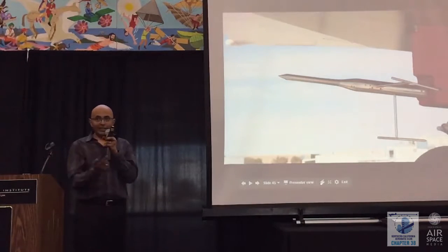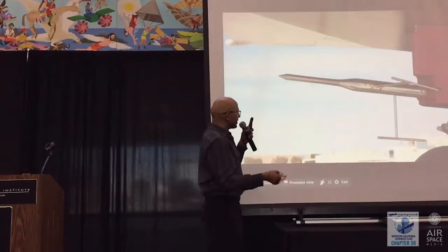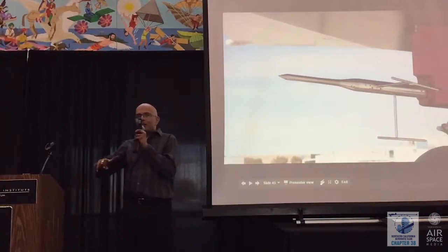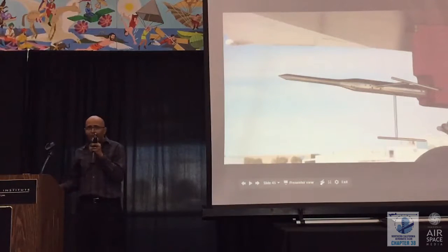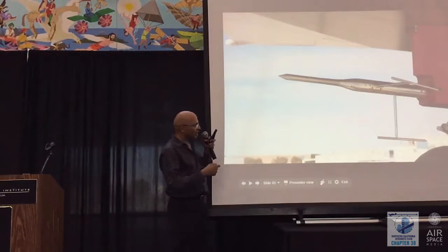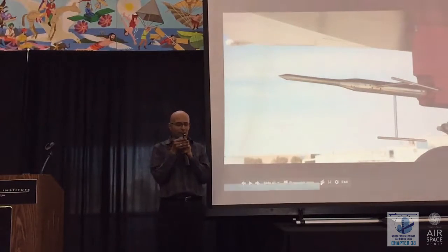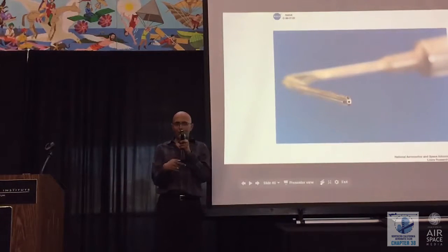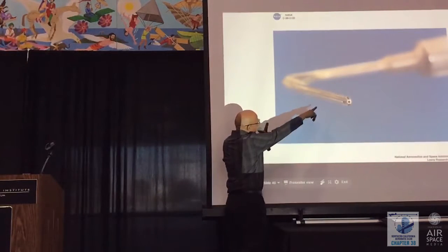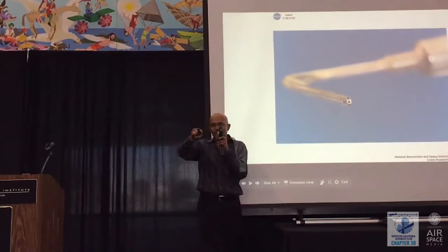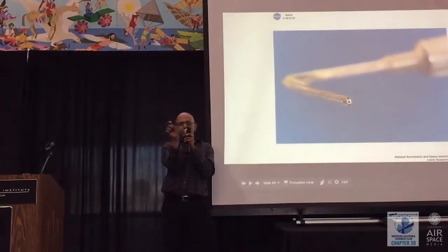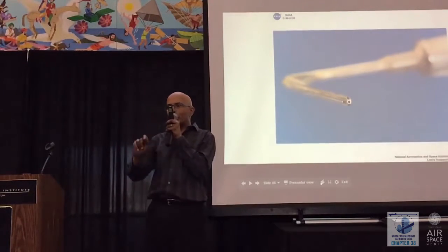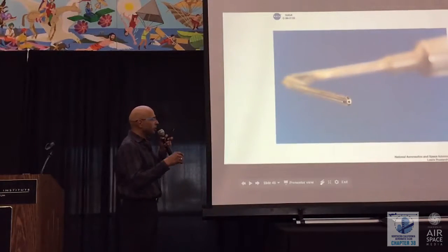So in flight testing, like if you're NASA, you build these really complicated probes to measure all the details of the airflow on an airplane that you're testing. These, as you would imagine, cost many, many thousands of dollars. We don't have many thousands of dollars. This is another example of a somewhat simpler probe called a 5-hole probe. So basically what people do is they make 5 holes, a central hole which measures how fast the air is going, and then 2 holes up and down, and 2 holes left and right, and depending on how much you're skewed into the air, this tells you by measuring the pressure difference how much you're skewed.